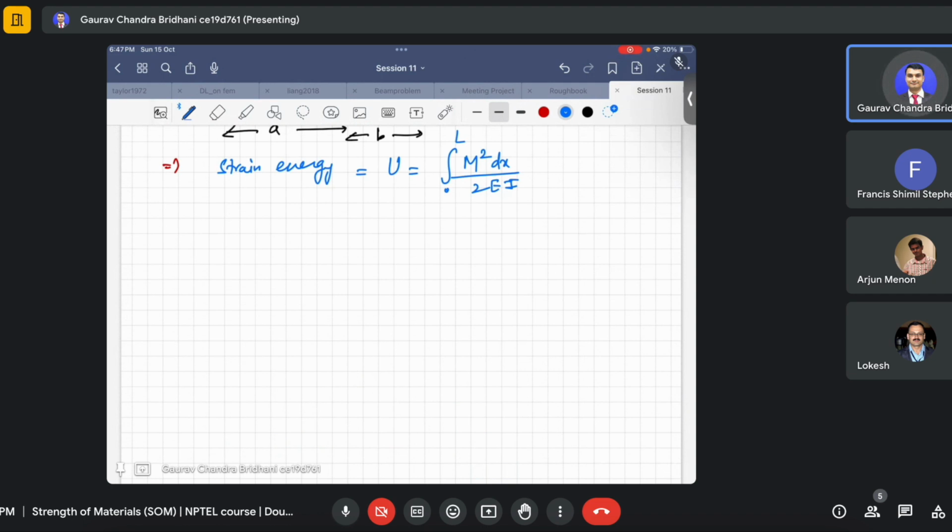So we saw in the lecture how the professor found how small the deflection in a beam due to shear is, and how large the deflection due to bending moment is. So we can easily say that most of the deflection in a beam is generated due to bending moment. Okay, so we can very easily ignore shear at this stage for shallow beams. Something different happens when the beam depth starts increasing, and that is another very interesting fact. Okay, so we don't need to go there.